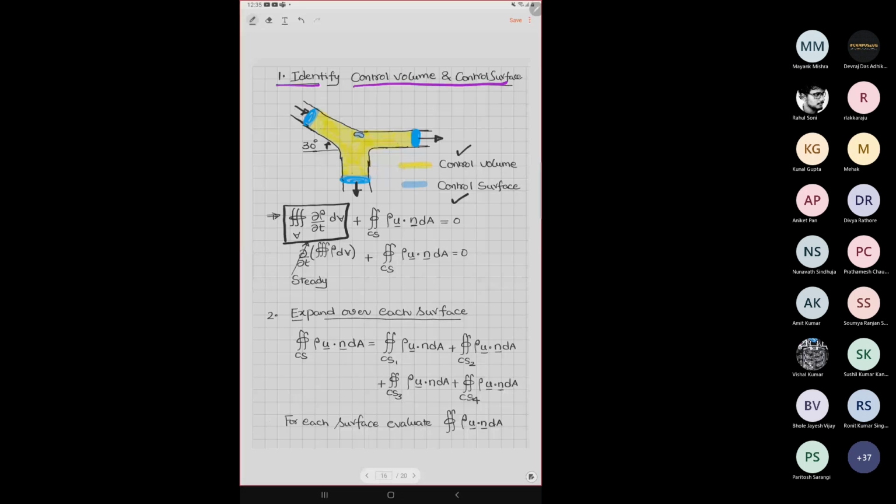That means all the time I will see the same V1, same V3, same V2. If I take picture after picture with a camera, the flow entering the control surface with V1 should not fluctuate with time. It should not fluctuate at V2, at V3, or even at the leak. If that happens, we will call that process a steady state process.